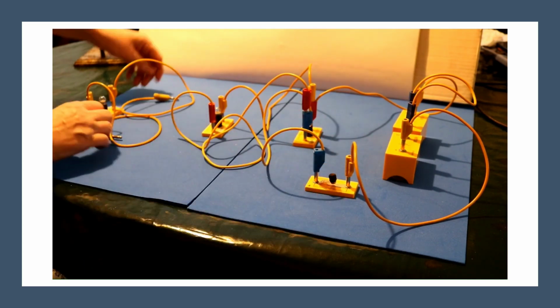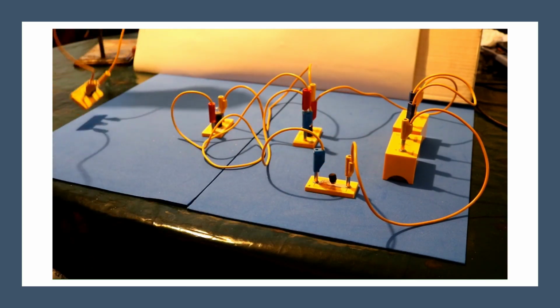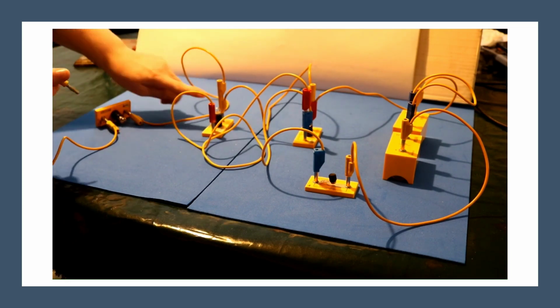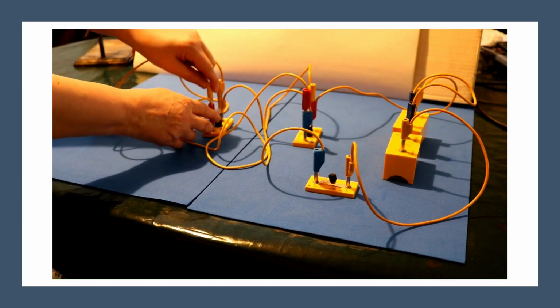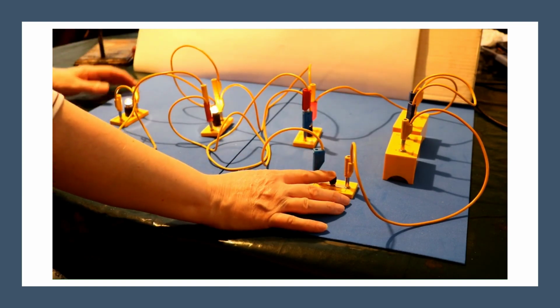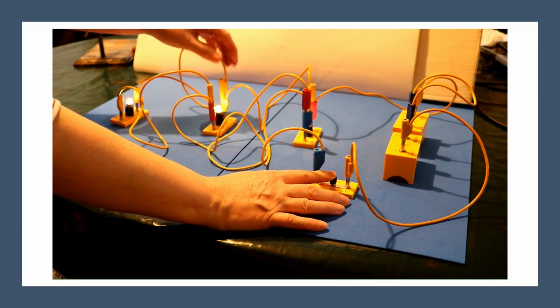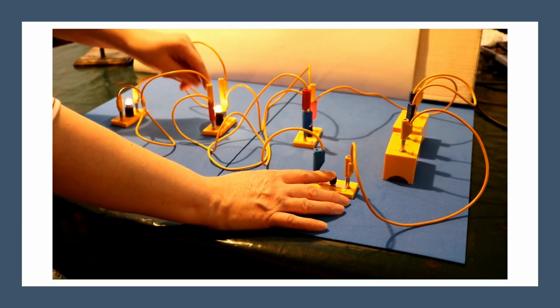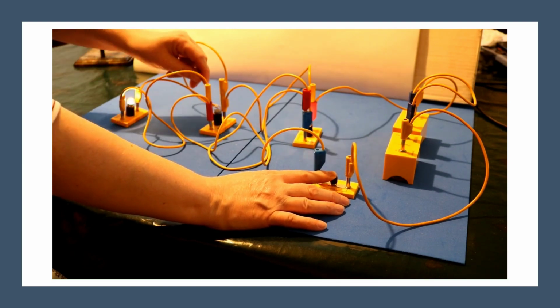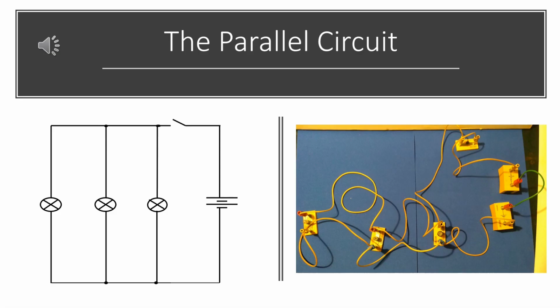And then I can connect up my third lamp in exactly the same way, 2 additional wires. This is how you'd show a connected wire. I'll get the circuit diagram for you later. Now they should all light. Doesn't matter that they're not the same brightness. Again, I can undo any of these and the others stay on. So the one on the left is the circuit diagram, the one on the right is the actual circuit built.